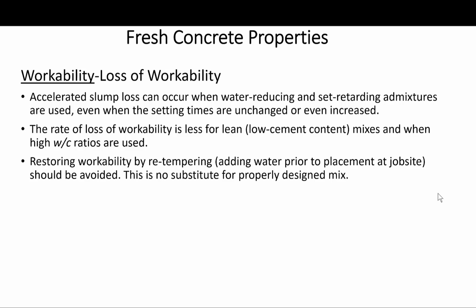If there is a potential for loss of workability for whatever reason, due to hot weather, windy conditions, or whatever conditions, that should be addressed during the design of the mix by selecting the proportions correctly, by using superplasticizers, or by other means. But adding water at the job site should be avoided completely. End of the story, okay?